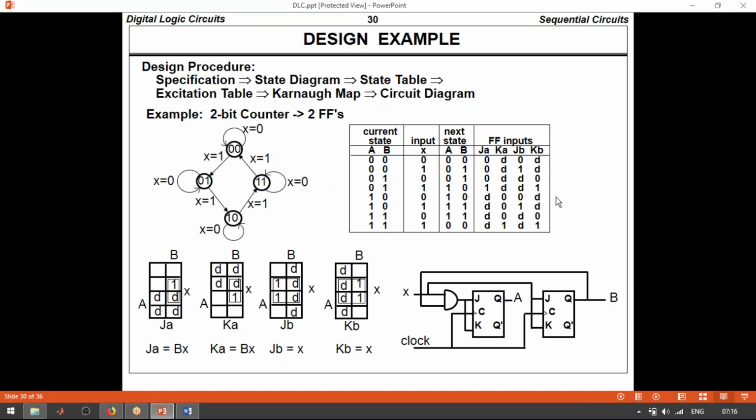We got it. Similarly, in any question, if they are asking for different flip flops, you have to use the truth table for that particular flip flop, generate the excitation table for the flip flop, and draw the diagram like that.